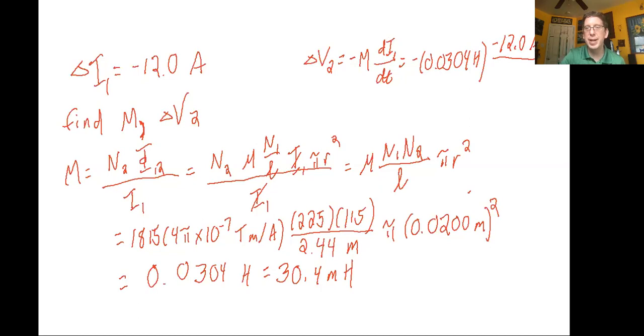And you're dividing by the time, and so that's 9.80 milliseconds. So in seconds, that's 0.00980 seconds. And so you get the voltage out of that. Now notice the negatives cancel each other out. And when you plug this in, you get 3.72 volts, and it's positive 3.72 volts. So what's the significance of the sign here?